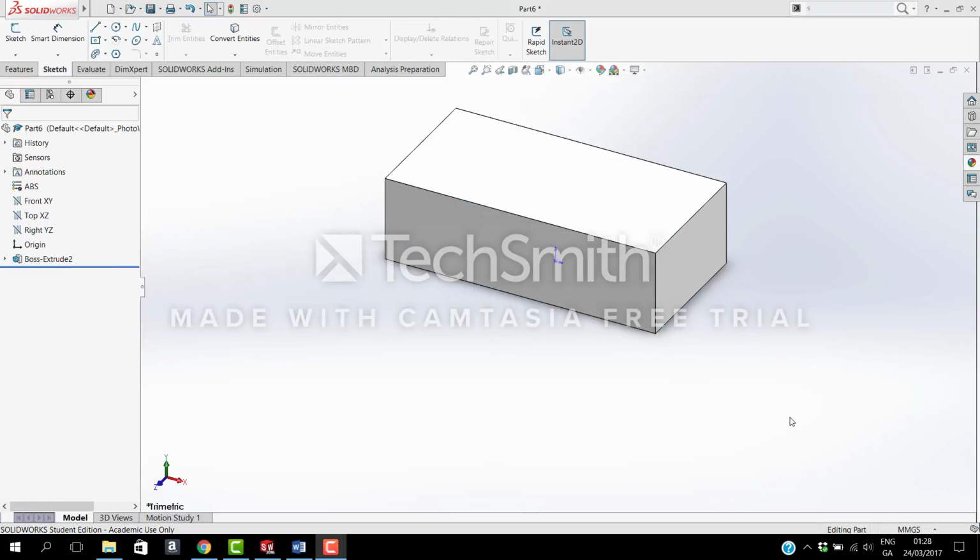The next step in my model is creating 8 identical circular extrudes on the top face of the block. I can use the pattern feature to do this. The pattern feature is used when creating multiple instances of the same feature. So first of all, I'll have to create my seed feature, which is the first feature. I'll do this by creating a circular sketch